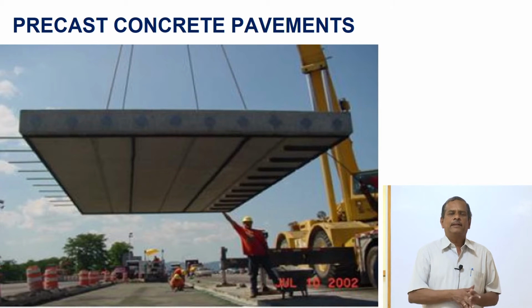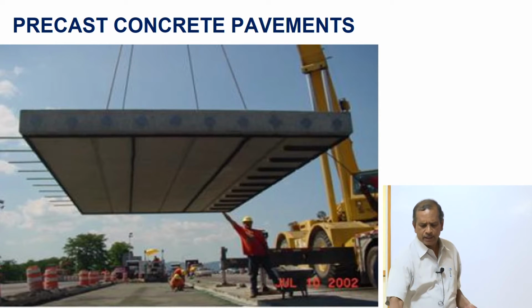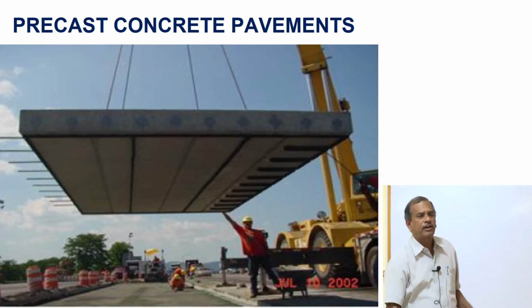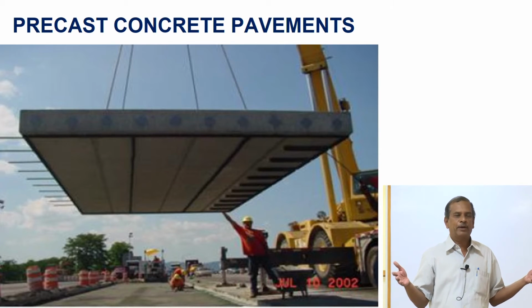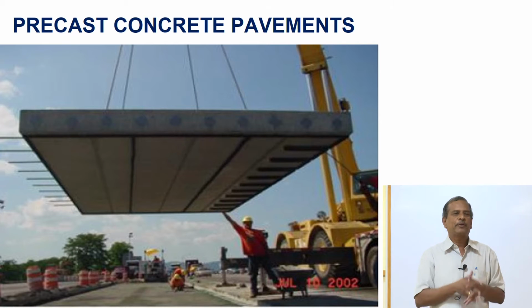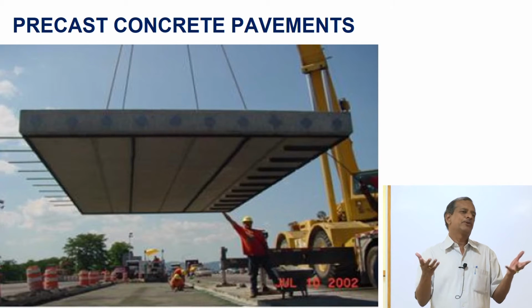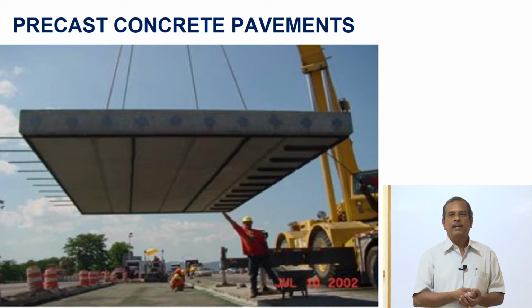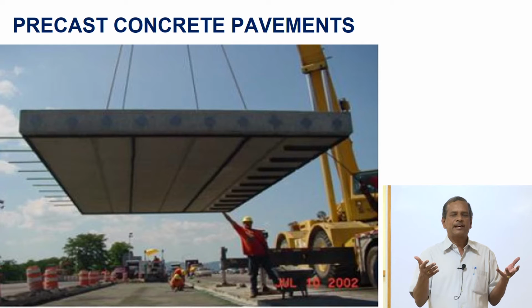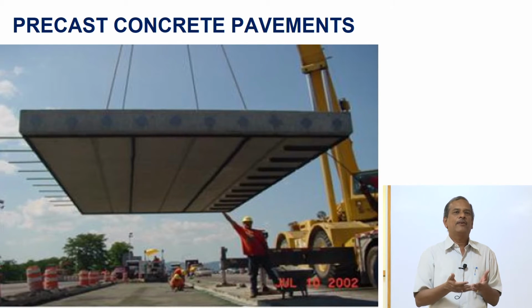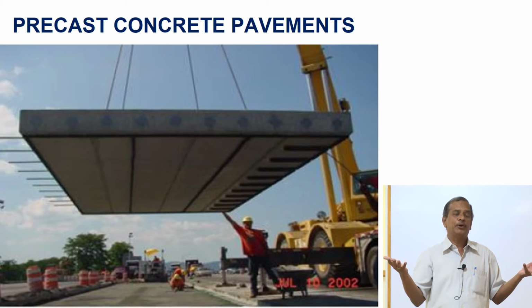Another thing which I have to introduce is that you can try to have a concrete pavement. As you know, the concrete pavement, you should cure it for 28 days. You can open the road to traffic only at the end of 28 days. Now, those of you from Bangalore will know, a number of roads have been taken up as white topping, a concrete overlay over a bituminous pavement. So I can construct around 300 meters, 400 meters per day. If I have to have around 200 kilometers, 300 kilometers of roads, it takes a number of days to construct these roads.